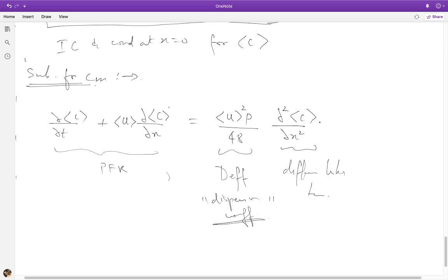And this effective diffusion-like term in x really represents axial dispersion, which, remember, owes its origins entirely to the non-uniform convection. So you can see how the averaging method with perturbation theory has really given us a way to explain why dispersion, which is convective in origin, behaves effectively like diffusion in the x direction.